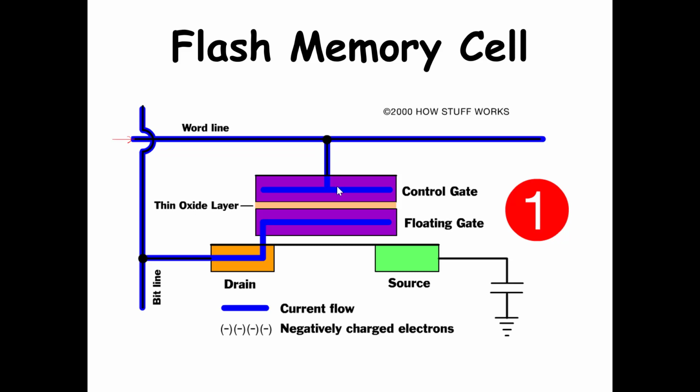So the role of this word line is to control the control gate such that either electrons come up or they come down. And whether a cell is programmed or not can be found out because the electrical properties of the cell change if you have electrons trapped here or not, right? So this is quite easy to find in terms of the current-voltage characteristics of this transistor.